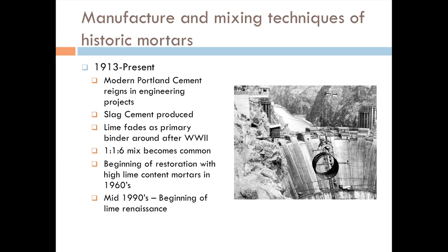From what I've heard, they had to run water conduits through this massive dam just to keep the whole thing from exploding or getting too hot. It had to be cooled down in some way or another. We get something else called slag cement. Slag cements are blast furnace slag, left over from steel manufacturing. Those would be ground down, used as a pozzolan, mixed with lime, voila.